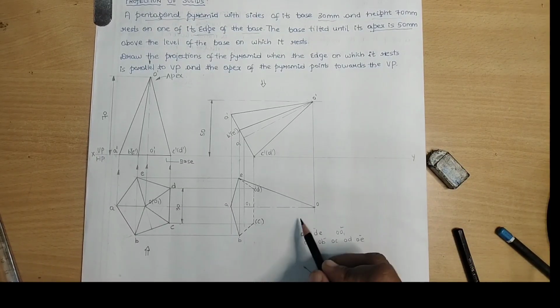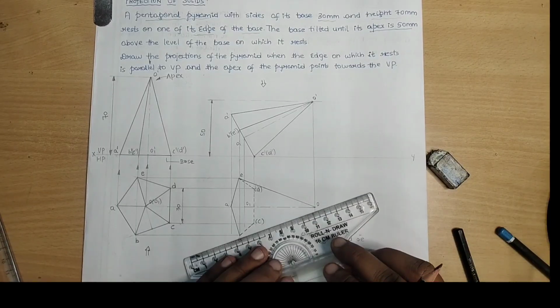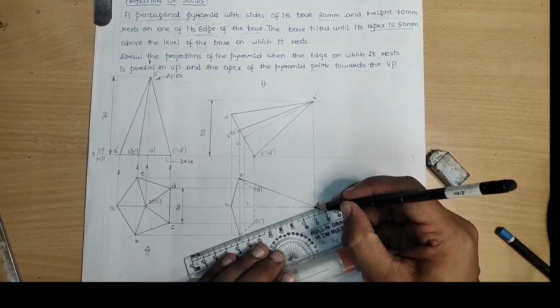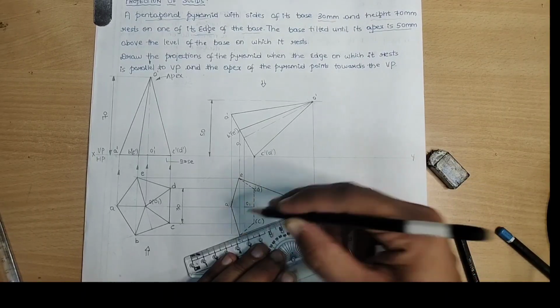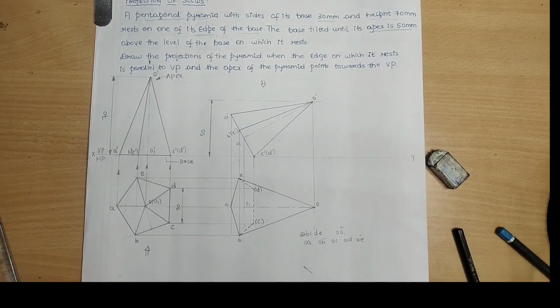On the same line of explanation, O to B, O to E is constructed. This also is visible. The reason is, in the fourth position, that is the apparent position, O to B forms the outermost boundary. Henceforth, it is visible.